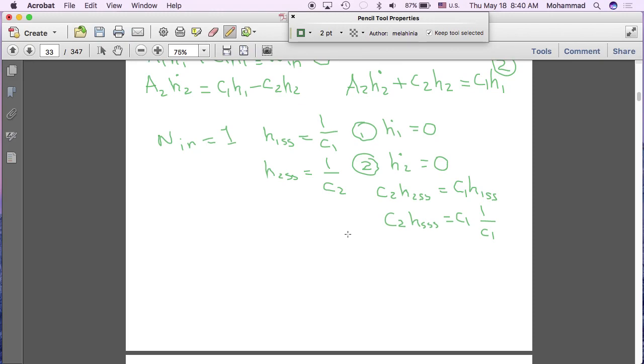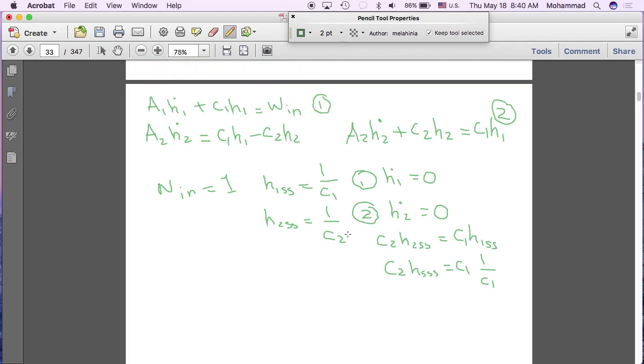Okay, the next question could be, what is the time constant of each of these two tanks? Can you find them? In order to find the time constant, you need to create the standard form. The standard form, if you recall, is Tx dot plus x is equal to a constant multiplied by u, or u divided by a number, the same way you could say u multiplied by a number.